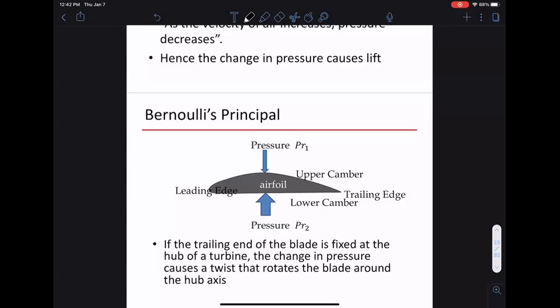Right. So the reason this is wrong, there are fairly simple thought experiments pointing to this not being quite correct. Most of us have probably made paper airplanes before. If you make a paper airplane, the wings, the airfoils, are completely flat. There's no curvature, no difference between the length above and below the wings of a paper airplane. A paper airplane flies fine. It can fly a fairly long distance.